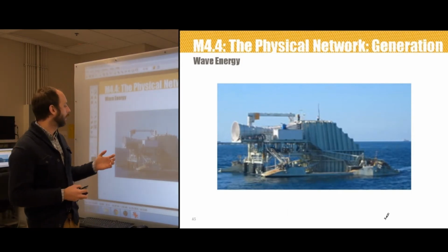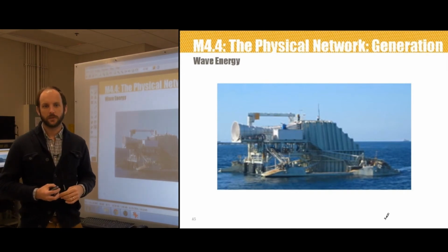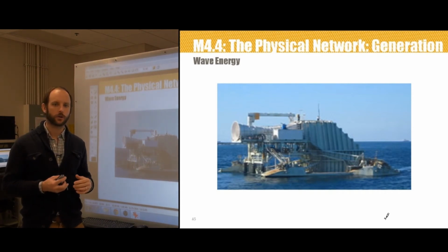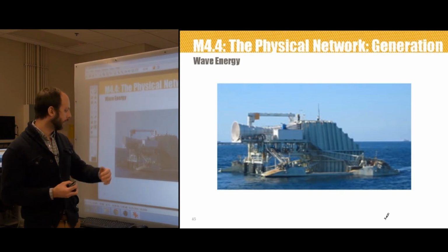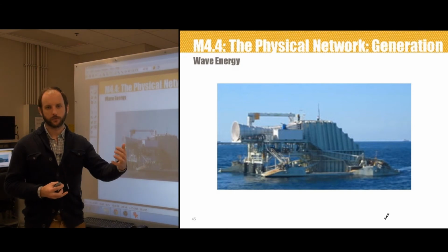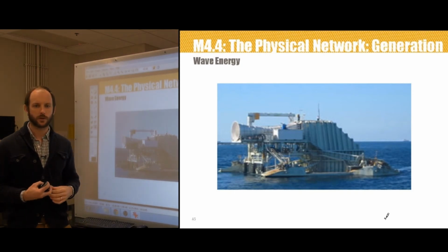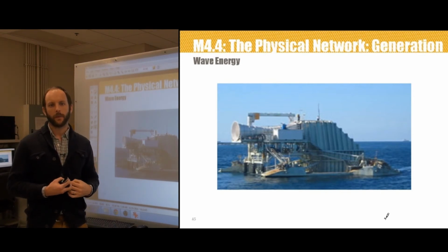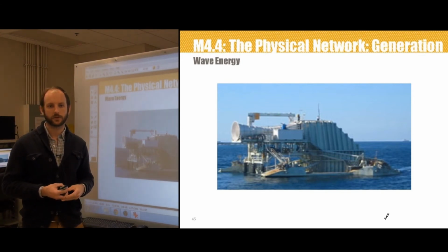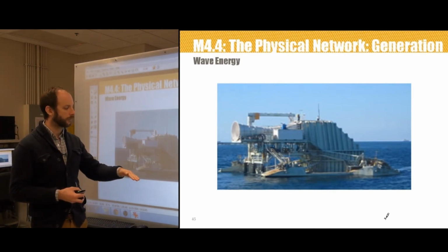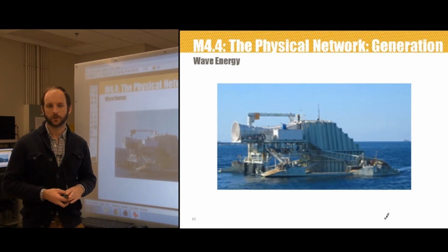So we've got a couple ways to capture wave energy. Offshore systems have typically been placed in water way further out than the tidal. Tidal are kind of close to the coast. Wave systems are kind of far away from the coast, usually in water depths of about 125 feet or greater, and they also have 3 methods. The first is called the Edinburgh duck, and basically what happens is as waves move back and forth, a pump goes up and down under the motion of the wave.